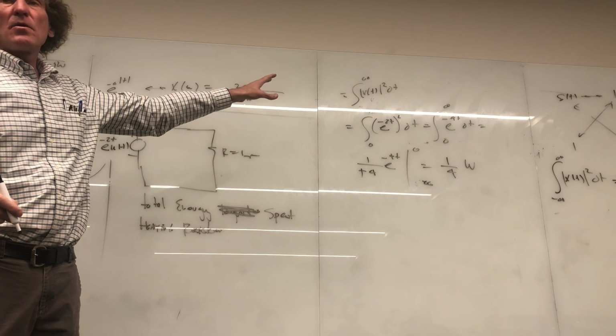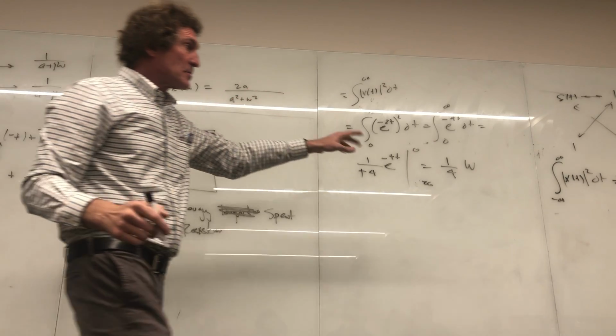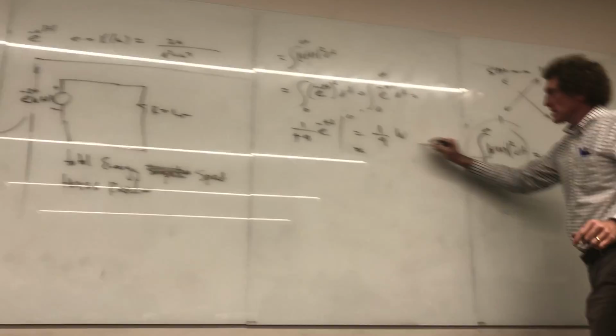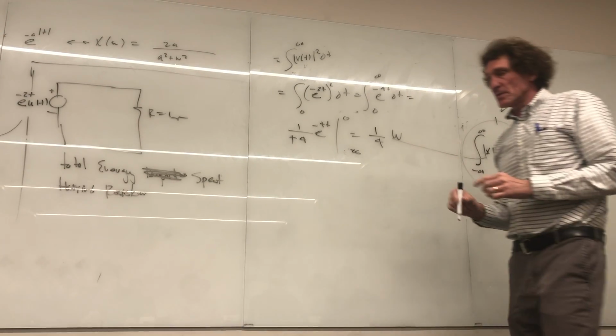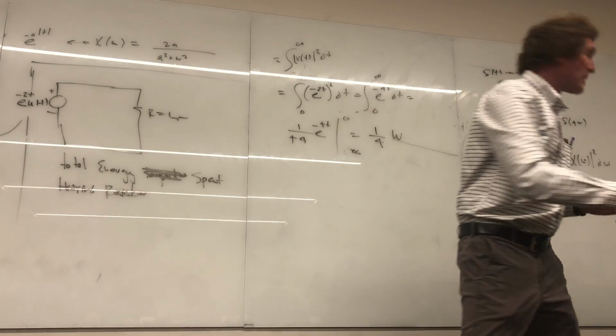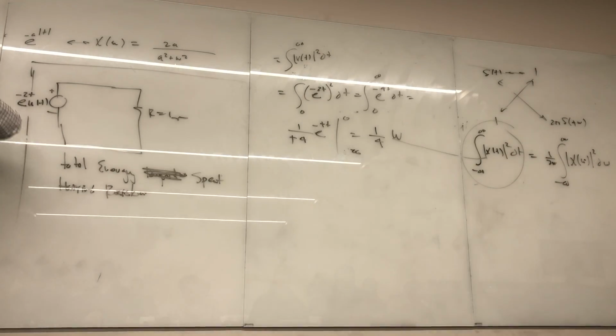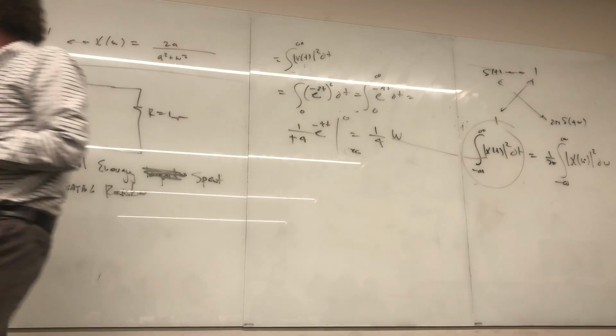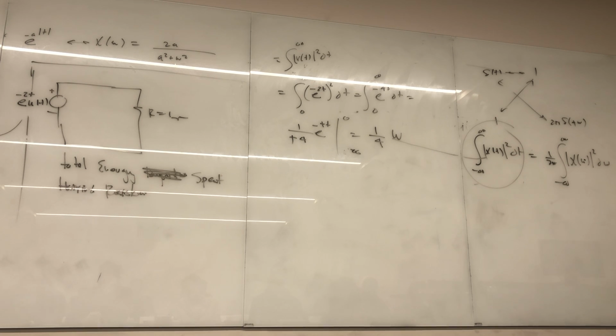All right? Now, get the same energy, only use this transform right here. We got 1/4 doing it that way. So if we wanted to do it the other way, I say that I know the transform of e to the minus 2t u of t, x of omega, is equal to 1 over 2 plus j omega. Does everybody agree with that?